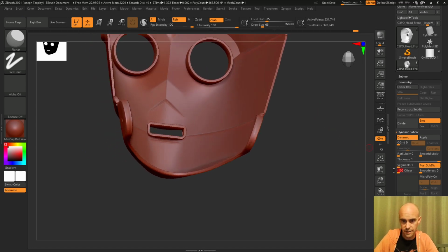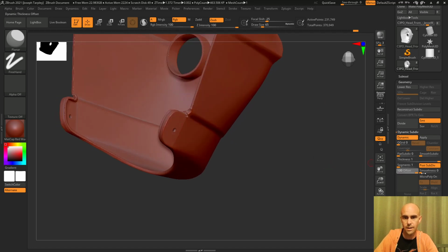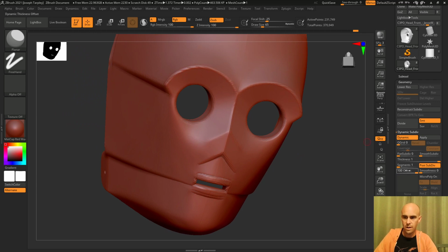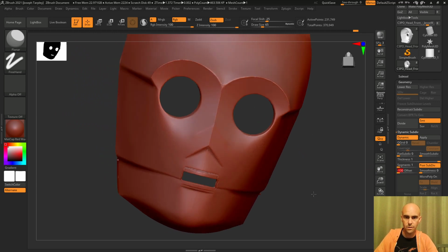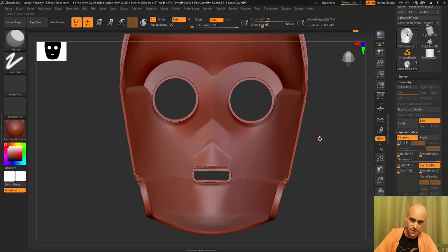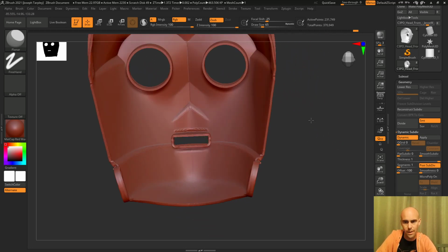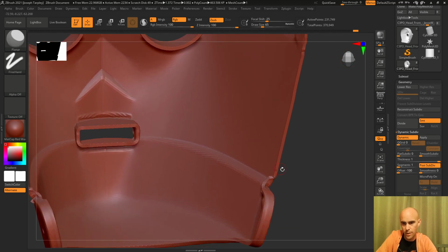Now you can offset that like this. You want to do negative 100, otherwise it adds the thickness to the outside, and so you can see it gets puffy and weird, but you want to do negative 100. So now the outside looks the same, but now the inside picked up the thickness here. Now this is probably like 1.5 millimeters.